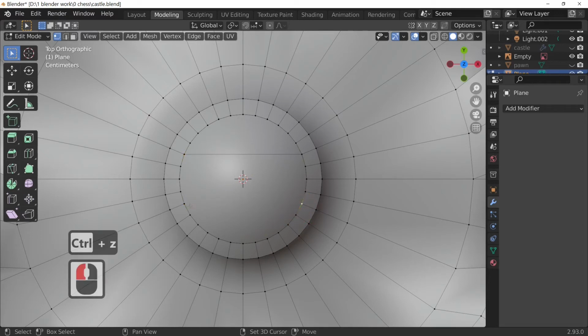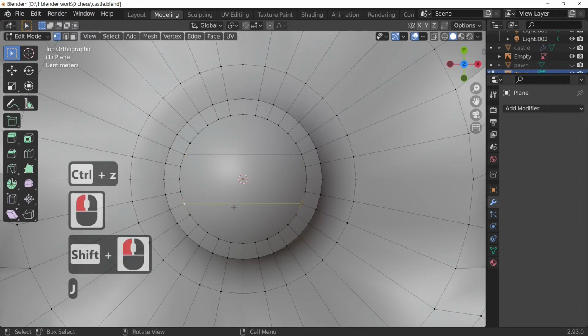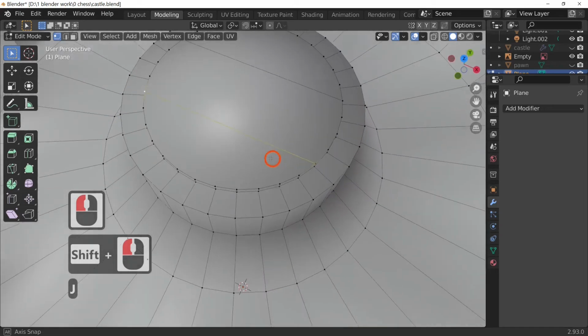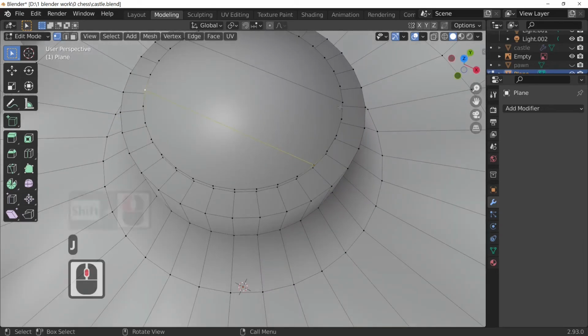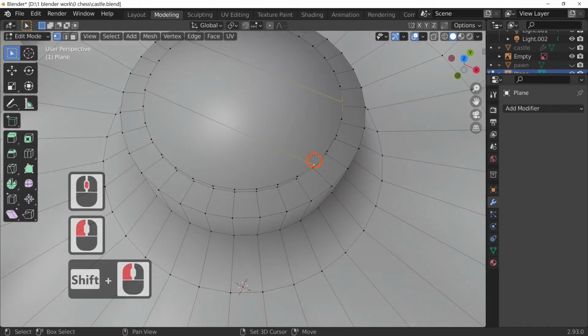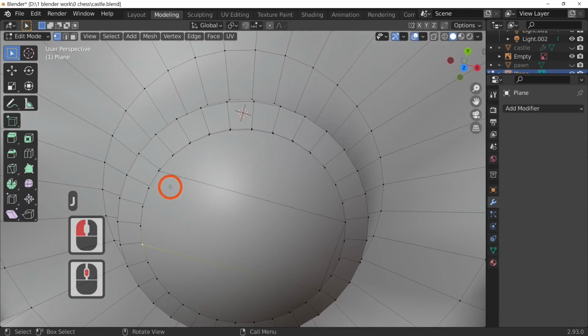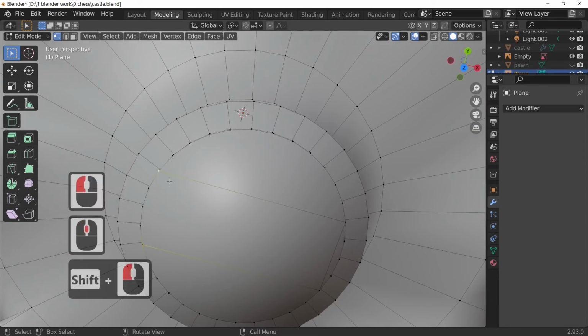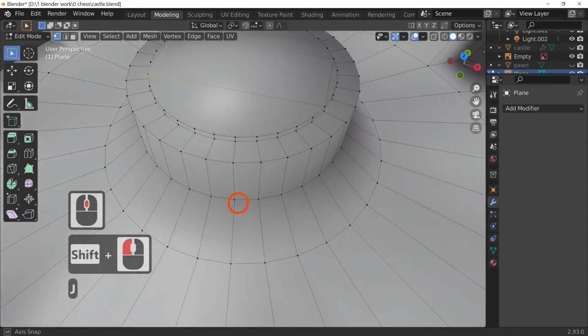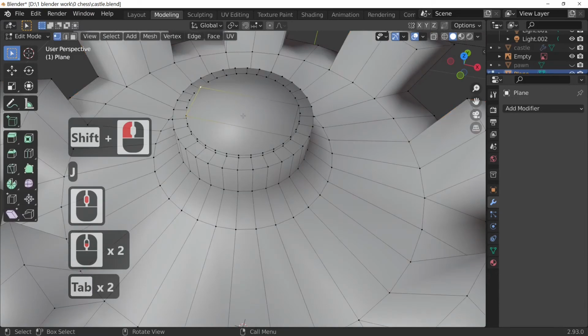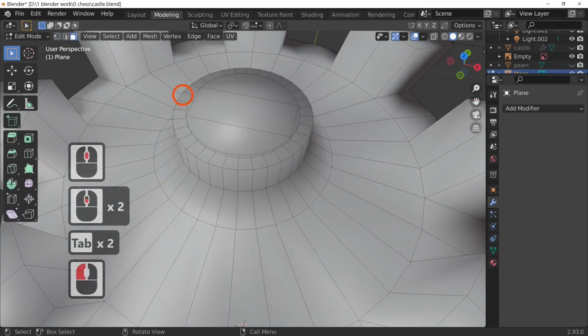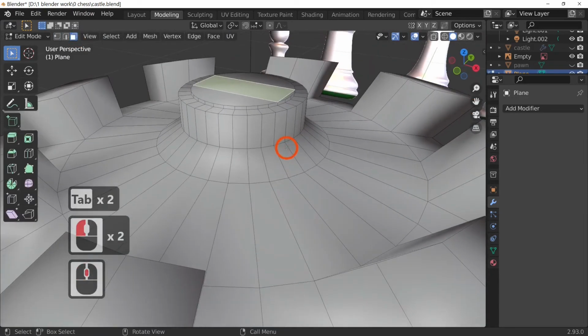So just select that point and select that point, press the J key, and it'll put a joint across. And then all we've got to do is select that point and select that point, press the J key, and select that point and this point and press J again. As you can see, we've now got a face there, which we can select if we wish.